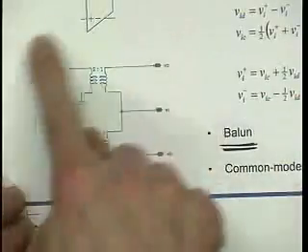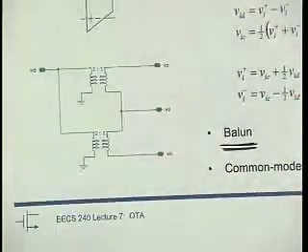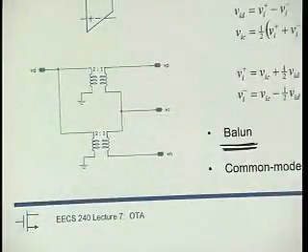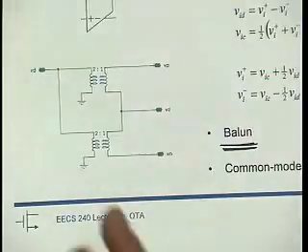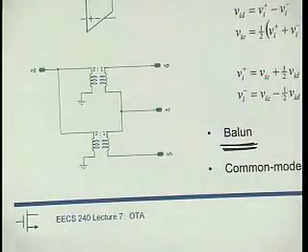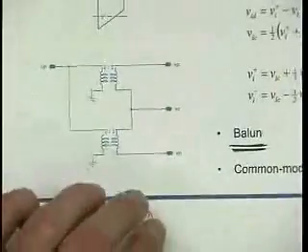So I suggest, much like the references that we talked about earlier, hack that into SPICE, make sure that it's actually working, put a sub-circuit statement around it, and put it into your library that you're going to use from now on. Probably this is one of these things that is still going to be useful 20 years from now. Okay.